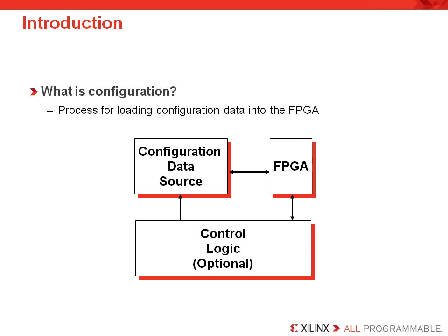In some instances, customers build their configuration scheme to include multiple configuration modes, so they can test and debug their system through one configuration scheme and then configure their FPGA through still another scheme after the product has been released.